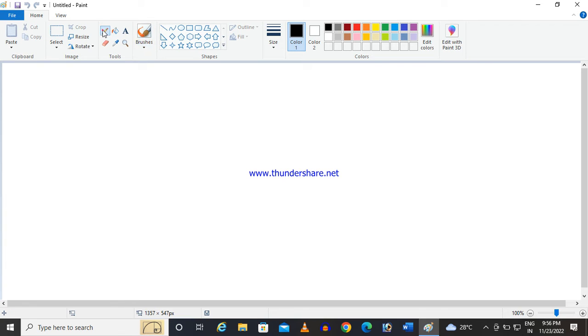So to understand the crack, the first thing to understand is the stress concentration, how the stress concentration will change if there is a crack and we are applying some external stress. There are various modes of crack. Today we will be talking about mode 1, that is opening, when the crack is getting opened.